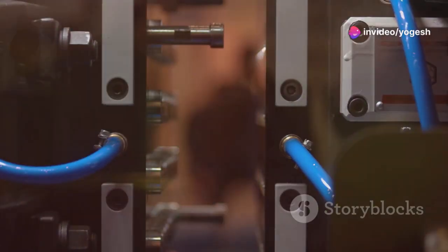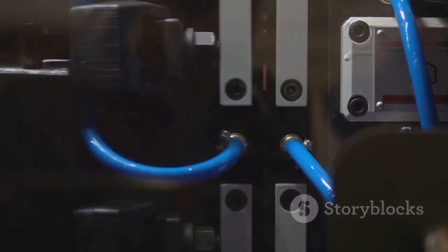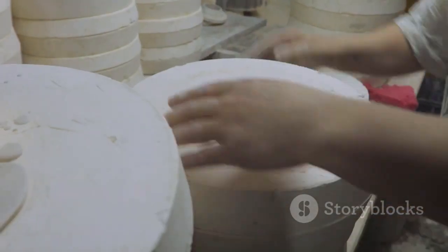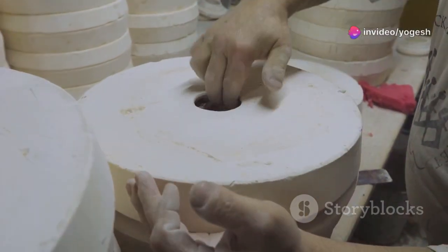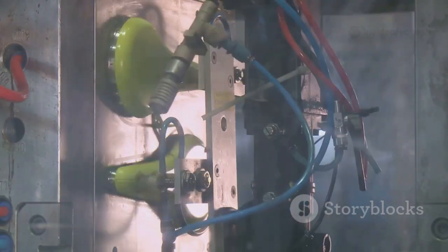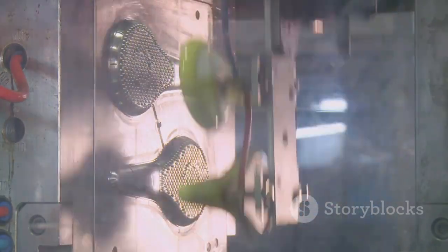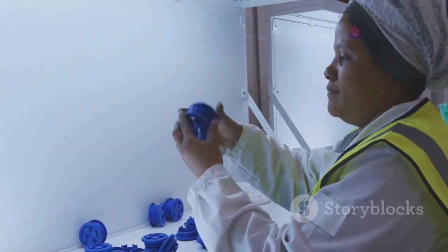We inject molten plastic into a steel mold, let it cool, then need to get the part out. Without a draft angle, the part sticks, scrapes, or even breaks during ejection. Friction and suction become your enemies. That tiny slope lets the part release smoothly, protecting both the part and the expensive mold. No draft? Expect drag marks, damage, and costly delays.